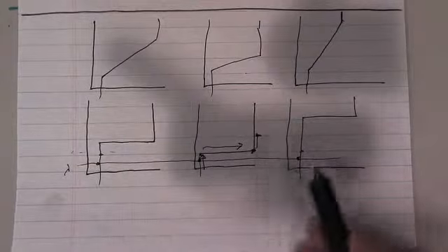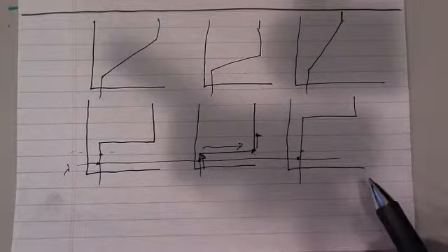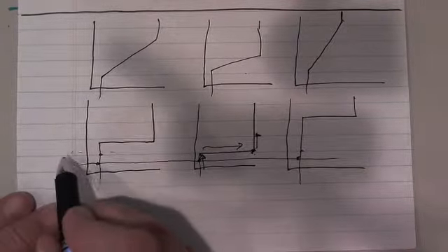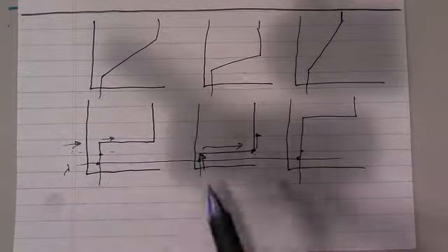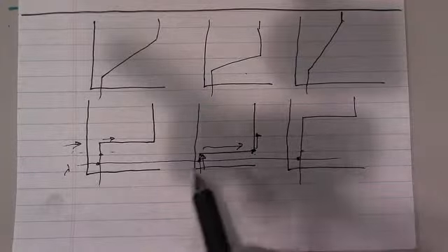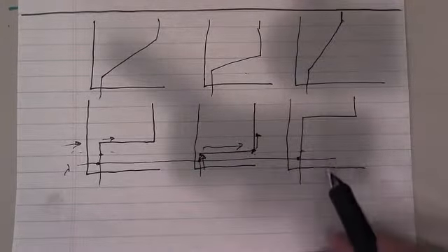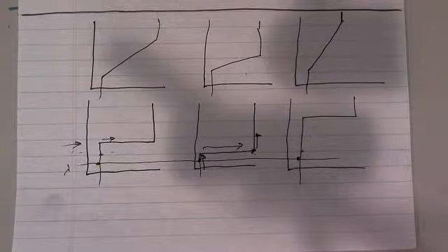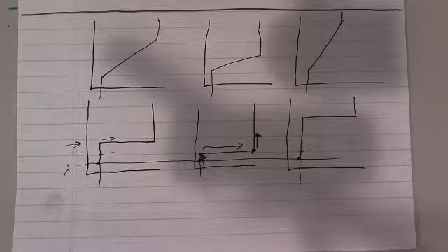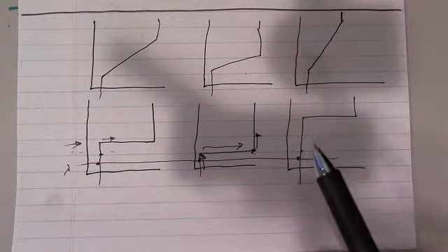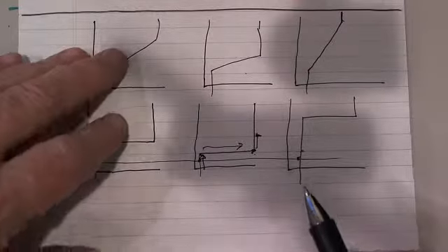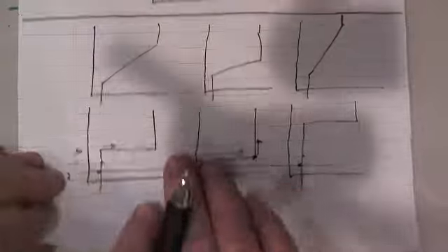Now, this min, this max, this min, if I'm still needing more generation, I keep raising lambda until I get to this point, and now this guy will go across. Eventually, I'm going to get P1 plus P2 plus P3 equal to the load that I'm trying to meet, which is 450. And that's the solution that you would get from this straight line function. See if that is what matches the LP. Then you go back,